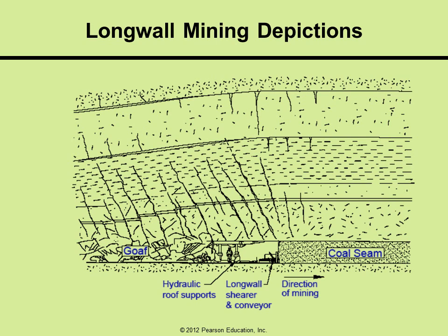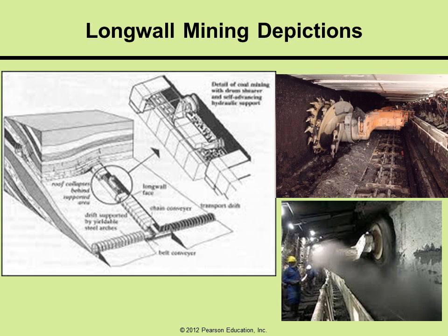So this is an example of longwall mining applied to coal, and as the face advances to the right, you can see that from the left the roof is collapsing behind the active face, after you remove the hydraulic supports and push them forward as the mining progresses. So here we definitely have failures, and this is a method very common, though not universal, in coal mines, but it is also used for other kinds of mineral resources.